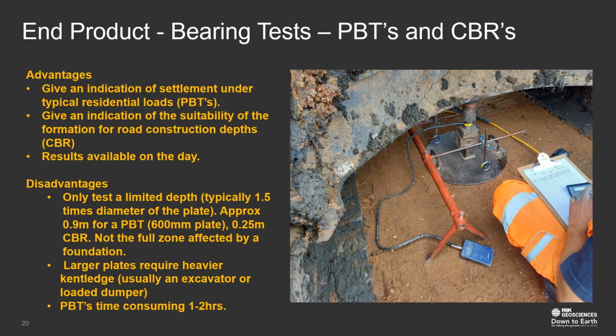The problem with using the larger plates is that, because they're larger, to apply the particular bearing pressures you want, you've got to have a heavier Kentledge to deliver that pressure and that mass that you're pushing off into the ground. And that usually requires tying up a loaded dumper or an excavator for a couple of hours while you're doing the test.